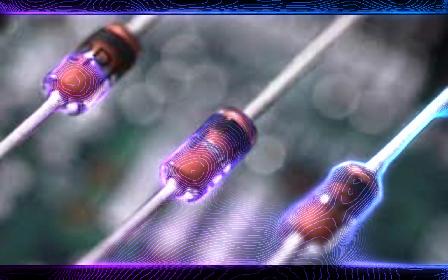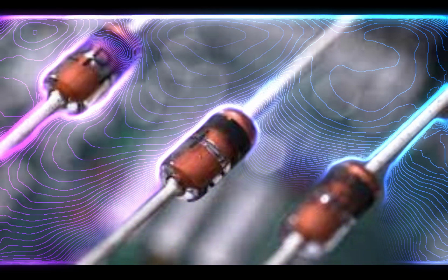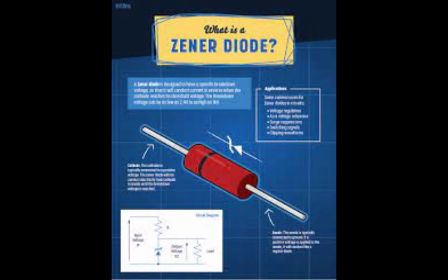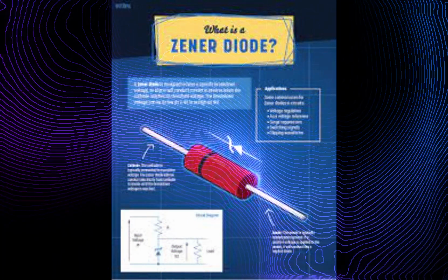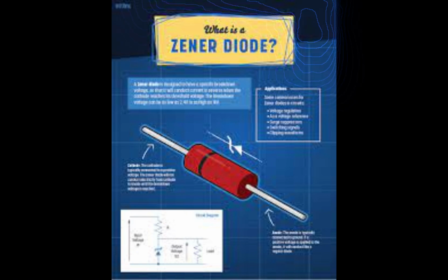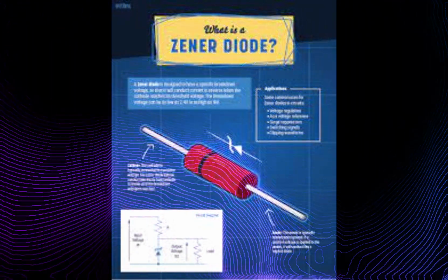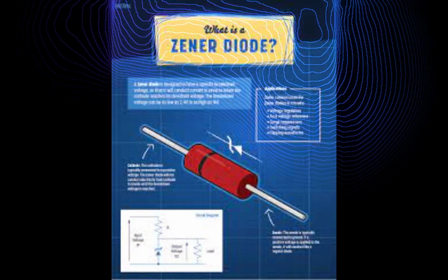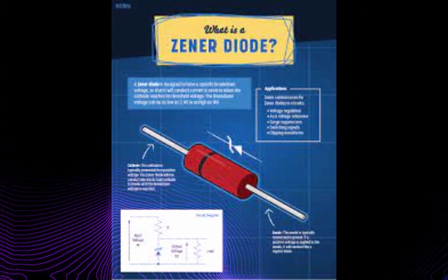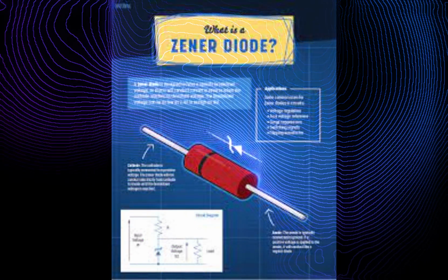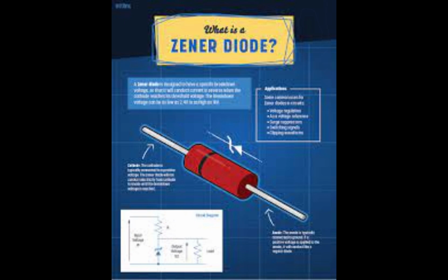As the reverse voltage increases to the range of the Zener voltage, current flows through the diode. Current increases to a maximum decided by the series resistor and then stabilizes, remaining constant over a range of applied voltages. Zener diodes have two breakdown effects.